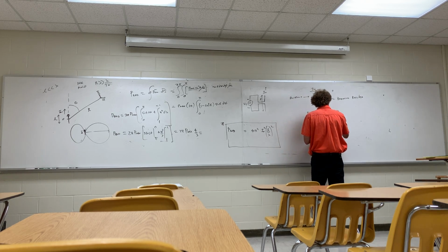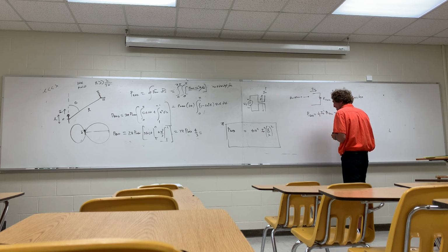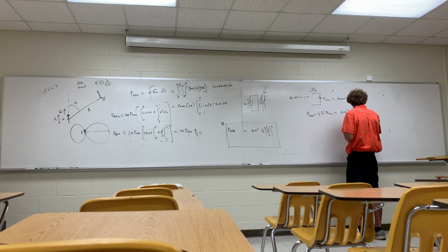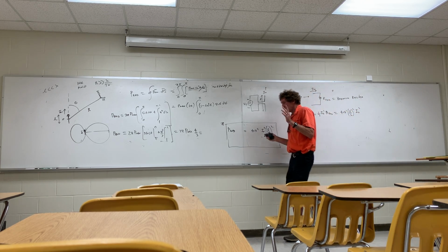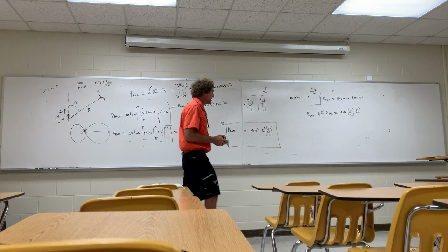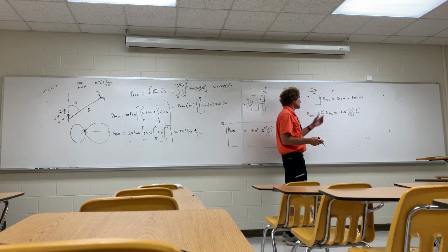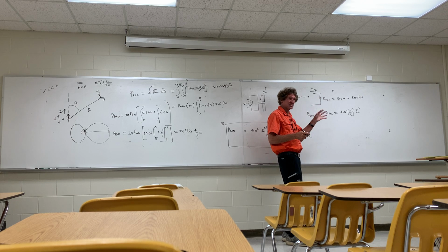And since the total power radiated was 40 pi squared times (L over lambda) squared, times I naught squared, I'm going to go ahead and just modify a few things there, but I've equated the total power radiated by the antenna to the power that would be dissipated by a resistor. The resistor was dissipating all that power.